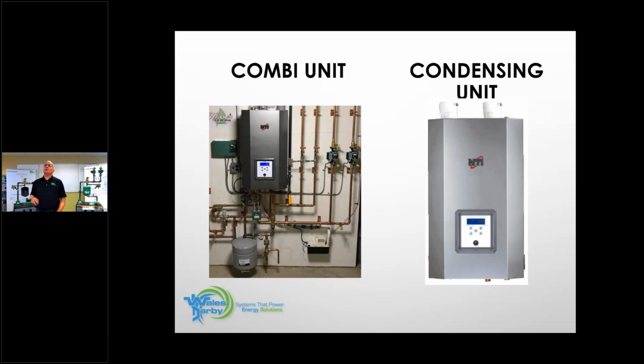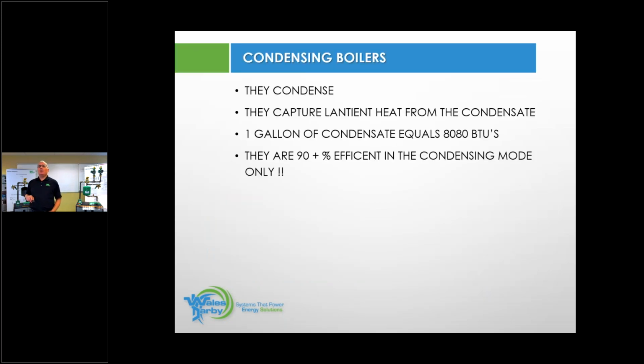But one of the reasons that we're talking about condensing boilers was we want to make sure that they condensate. And that means, what is the return water temperature we want to see? 130 degrees. Okay, so we do our heat losses, we do our math. We could take advantage of more baseboard than necessary if it was a replacement job. If it's a new design, we design the system so even on an average coldest day of the year, the boiler condenses, and that's how Mr. and Mrs. Smith are going to get that 90–95% efficient system.